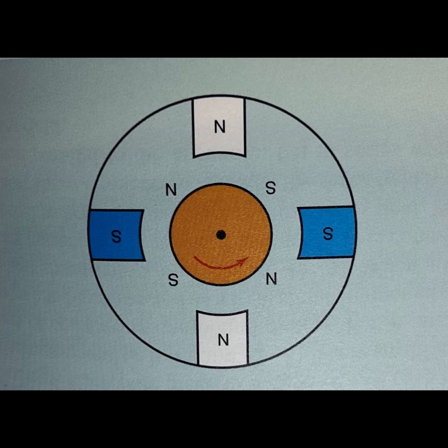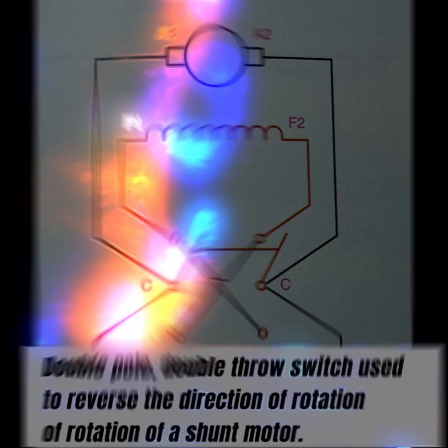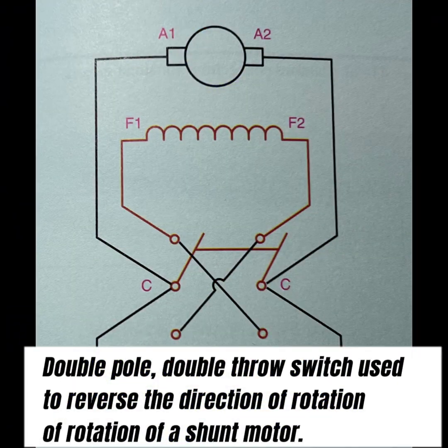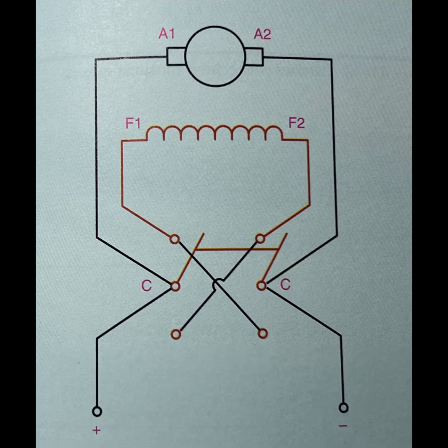Identifying the windings. Windings of a DC motor can be identified with an ohm meter. The shunt field winding can be identified by the fact that it has high resistance as compared to the other two windings. The series field and armature windings have a very low resistance. They can be identified, however, by turning the motor shaft.